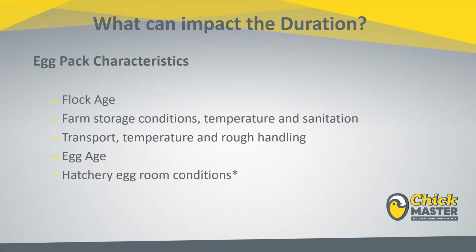So if I have a hatcher room that is, say, 75 degrees and say 50% relative, but I'm putting a high rate of ventilation through the hatcher machine, that rate of ventilation can cause, as the humidity peak occurs, you don't really recognize it on the graph, or you don't really recognize it in the machine because of the rate of airflow through the machine. And that usually has a bigger piece of control on that.